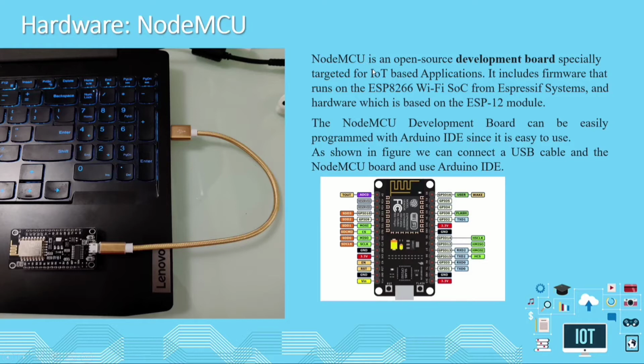I have used the NodeMCU for the project because NodeMCU is an open source development board and it is specially targeted for IoT based applications. Also, because it has the inbuilt Wi-Fi module in it, which I have used in my project. The NodeMCU is compatible with the Arduino IDE as well, so we can do the code in Arduino IDE, and it is very easy to use. We can just connect it, like I have shown in the figure,